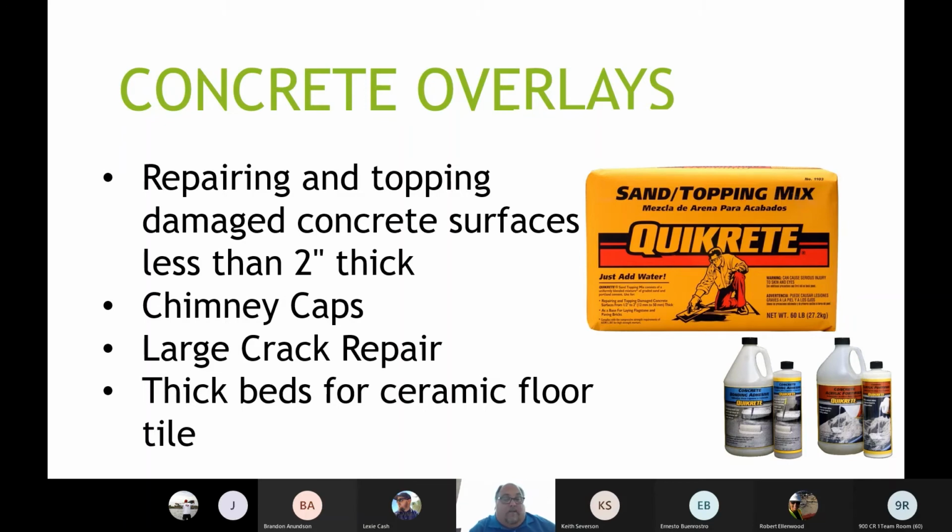And an important thing to know is that if you do use an acrylic fortifier in a material, be it doing a stucco patch or whatever, a lot of times in most conditions you don't want to wet cure it, you don't want to moist cure it. Part of the magic of the acrylic fortifier is it needs the air to help it cure. So you're suffocating it by either covering it, or by a moist cure, a damp cure.